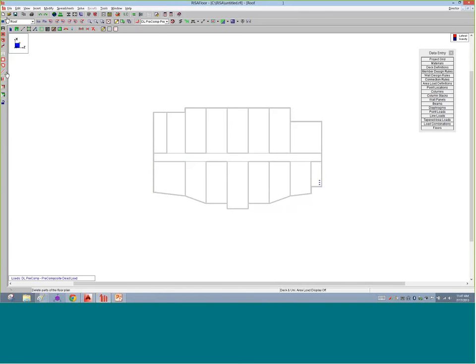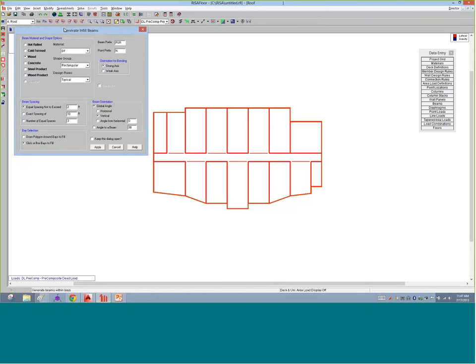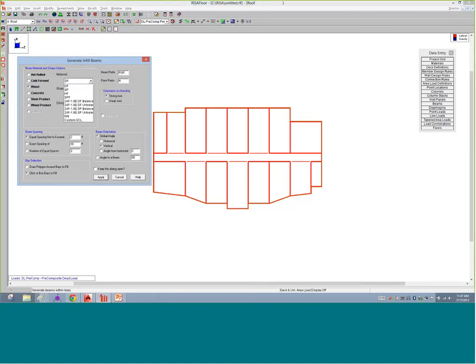Now they're gone. Now I still have all those awesome collector elements. I didn't delete that. I don't have to draw them back in, but I just deleted all the gravity ones. That's it. So now I can redraw. I can say let's draw this again. Let's use our infill beams. Let's make sure that these are glulam. We'll use them as glulam shapes here. We'll choose them to be glulam, and then we're going to say they're going to be vertical. Instead of horizontal, they're going in as vertical, and then they're going to be an equal.